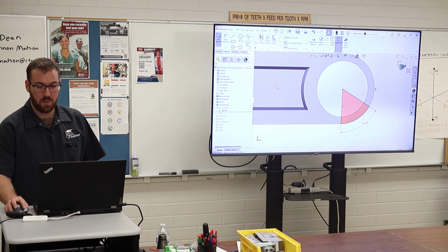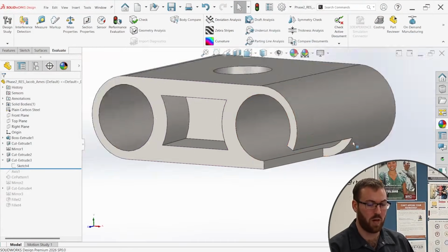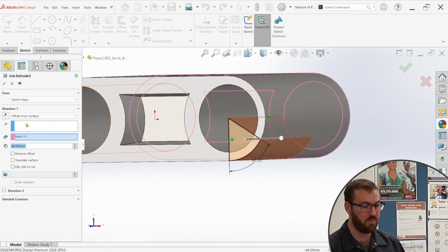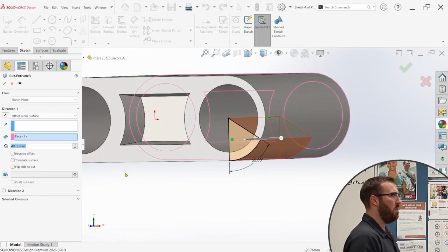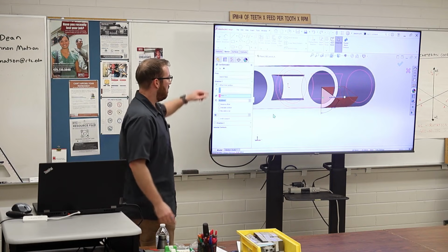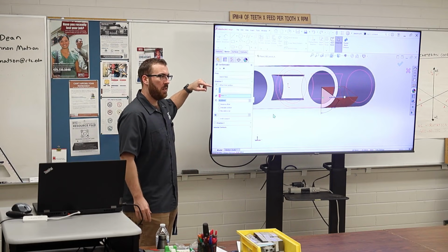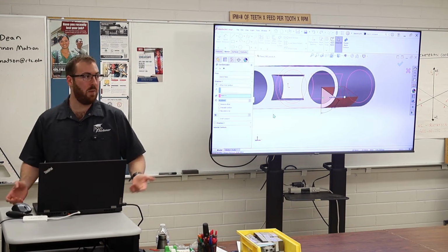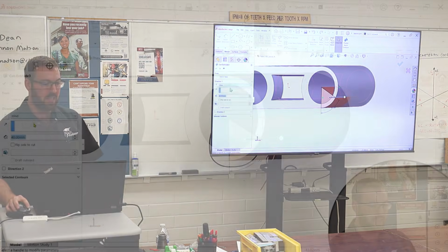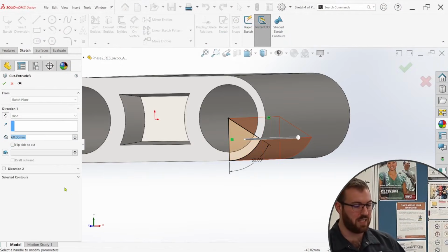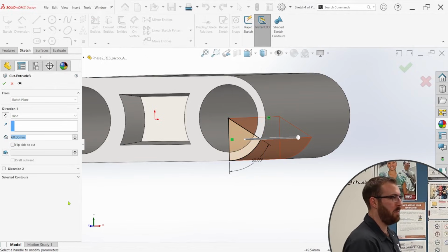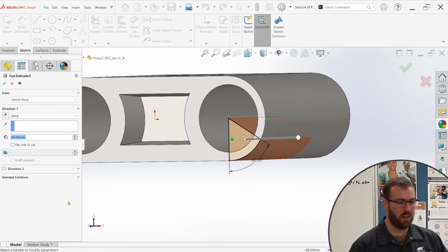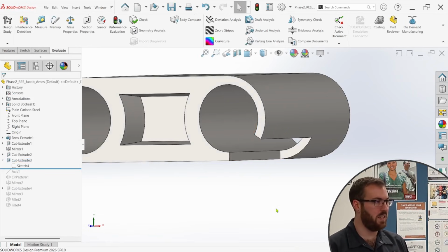And the cut depth can be approached in a couple ways, because again, this is the Wild West now. This is phase 2. We don't have to really care about design intent. If you look at the cut extrude feature, when I did this, this is kind of a mistake, but it's a very small one. I set an offset from surface end condition and used the 40 millimeter dimension that's specified on the drawing. So it's not a mistake, but I probably could have done it faster if I had set this to blind and done some quick mental math and set 60, because there's one fewer selection I would have to make. I wouldn't have to choose an end condition since blind is the default. Little details like that could shave off a few seconds here or there, but the result is essentially the same.